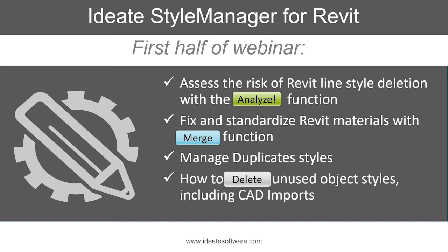A big contributor to this problem is what I mentioned: when you import or link AutoCAD or MicroStation or IFC or other CAD format data, the object styles get created in Revit, and especially if you import or explode, there's all kinds of stuff that gets created that doesn't match your standards. So we're going to look at how you can use Ideate Style Manager to clean up some of that.